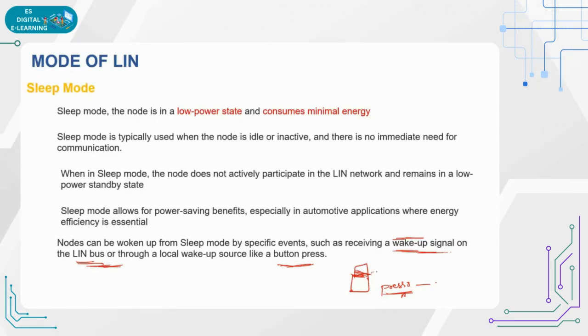It completely stops. Whenever you press, that press is the part of a wake up. So we are waking up the ECU, and then only the window will open, meaning the output will be acted on. That's how the wake up is considered. So this is sleep mode.